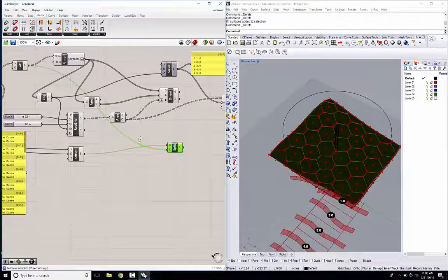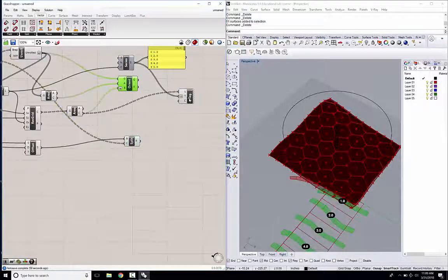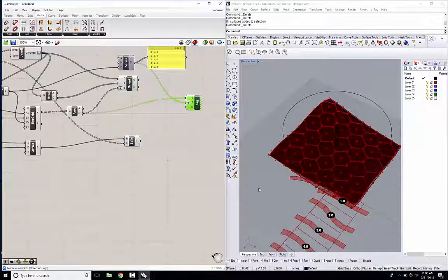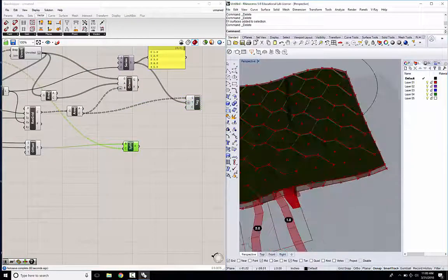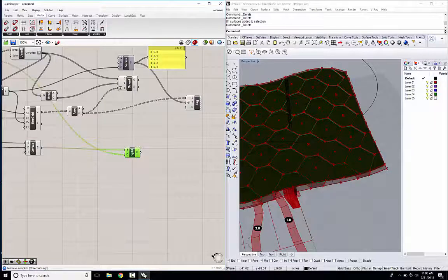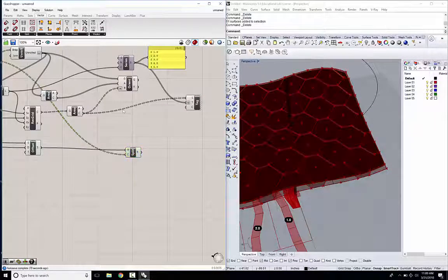We don't want to flatten it too much because we want to keep it organized the same way that these panels are so that we can find each shape when we go to unroll them. So with these split surfaces, we're going to go ahead and use that sift component again to sift for the area of each component.